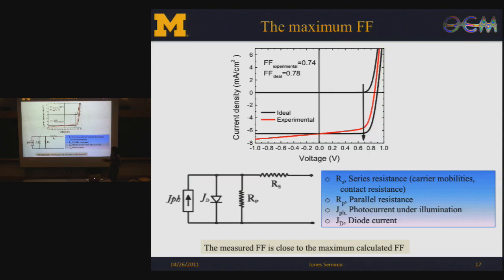So let's look at my organic solar cell. This is an IV current-voltage curve in the dark. In the dark, it shows the typical diode behavior. So suppose we are generating the photocurrent under illumination, and we shift the curve in the dark to this position, and this will be the most idealized IV curve I can generate from my diodes.